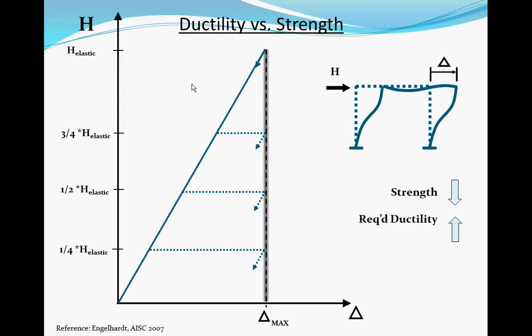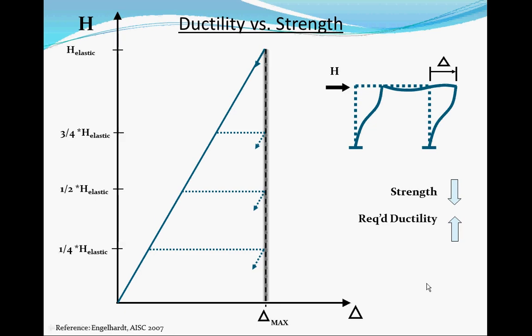But ductility versus strength. Typically, the higher the ductility, the less strength is required, the less loading. I wouldn't say it's contradictory, but that's what it is. The higher the R value, the smaller the seismic load you design for, and they give you the benefit of that. And that's why all these strength and ductility requirements are important, because you're actually designing for less load.